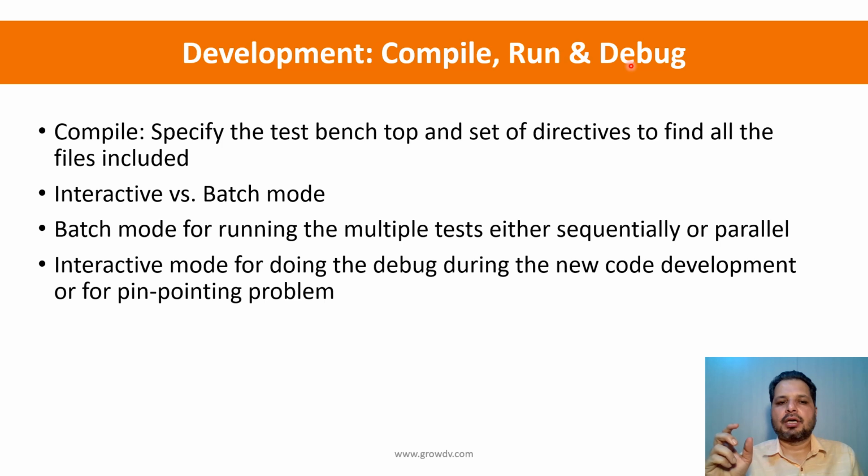Once it is compiling cleanly, in terms of performing simulation, there are two modes that are available. There is an interactive mode and there is a batch mode. As a part of your early test bench bring up, you would use the interactive mode. In the interactive mode, you get the IDE, and if you have used any standard interactive development tools, you know that you can put in breakpoints, do single step execution, and watch the values of variables.